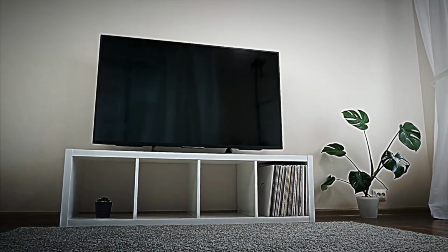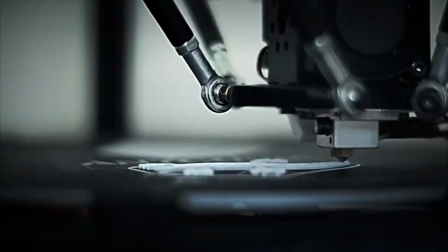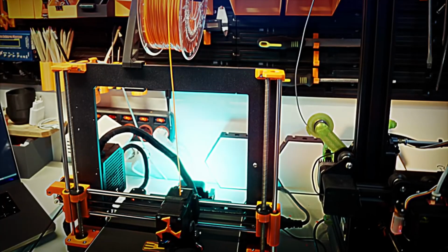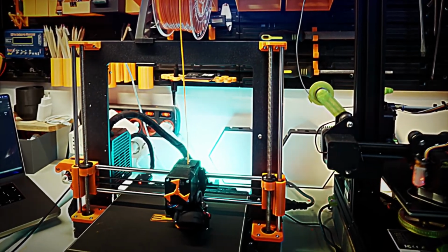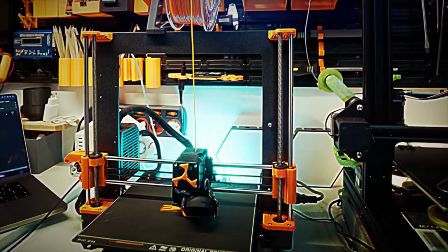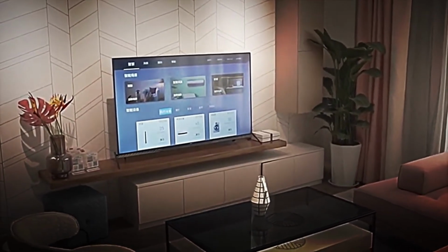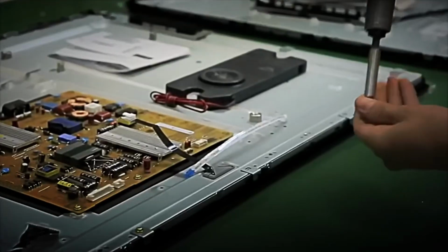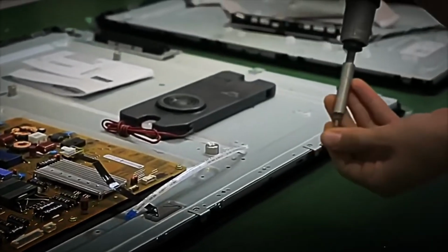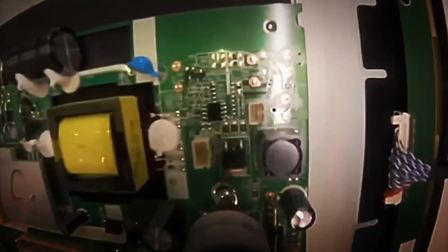and personality. The manufacturing of the casing is carried out using high-pressure plastic injection machines. Imagine liquid plastic being poured into precision molds that, upon cooling, acquire the exact required shape. These pieces, which can form the back, the sides, and the frame of the TV, are designed to be robust yet lightweight. The precision in this process is crucial because each casing must fit perfectly with the rest of the components, ensuring not only an impeccable appearance, but also resistance against shocks and falls.